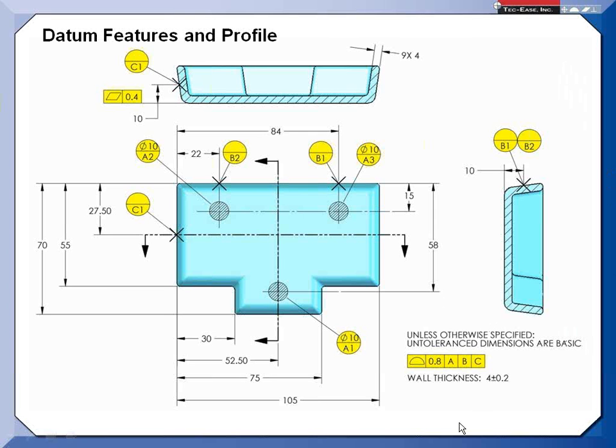More and more people are putting a general profile tolerance on their molded and cast and forged parts. You see I have a profile of 0.8 down here relative to the datum features. And I have targets, very common with castings and forgings and some plastic. And the question became, well, what happens to your profile tolerance if this profile applies all over this? As one member likes to say, it's kind of like a paint dip tolerance. You dip the whole part into paint, and that's showing you where the tolerance applies. But what happens right at those datum targets?